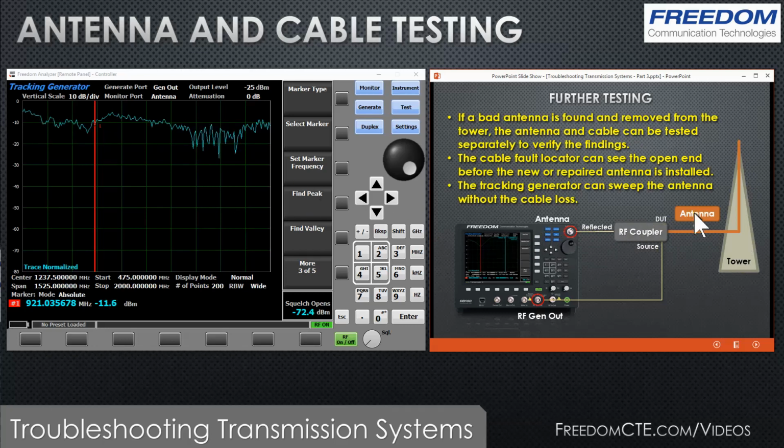But up until now, we have not had to replace cables. We have not had to climb towers, not had to guess. Everything has been pass, fail, and then we were able to determine the distance to the fault if there was one. So the practice of just swapping out parts really is no longer valid. That is the benefit of using the cable fault locator first, and then looking at the return loss across frequency to make sure that the antenna is performing properly.